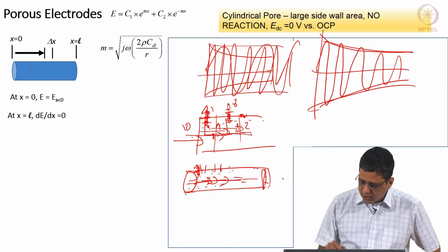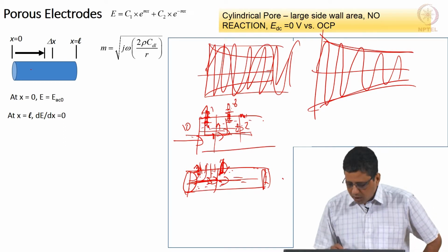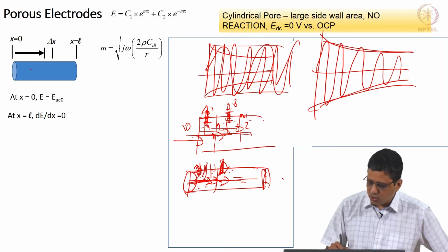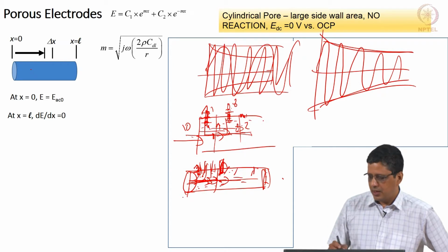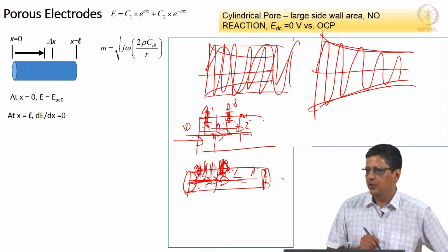If I want to look at the fluid flow here, I have to say whatever has gone out, because of this distance there is a pressure drop. The total pressure drop here will tell how much is the pressure here, and we can calculate the flow rate because of this. Whatever fluid that is coming here still has to go out through this only, and when I want to calculate the flow rate here, I need to know the local pressure, that is all I need to know, and the resistance.